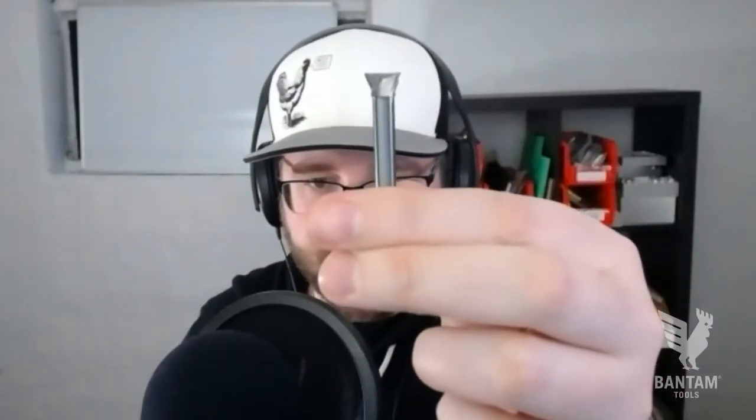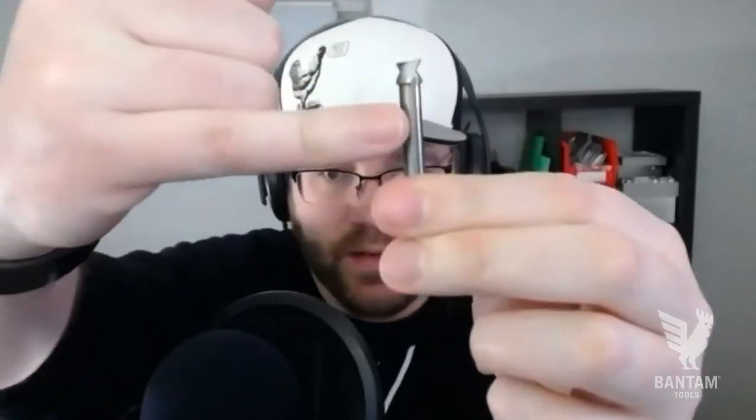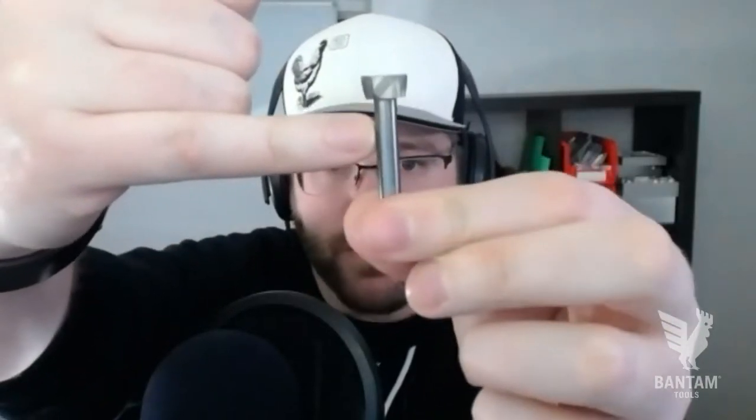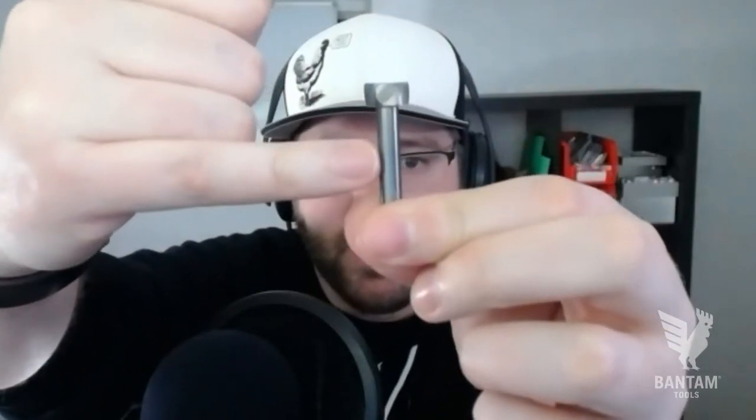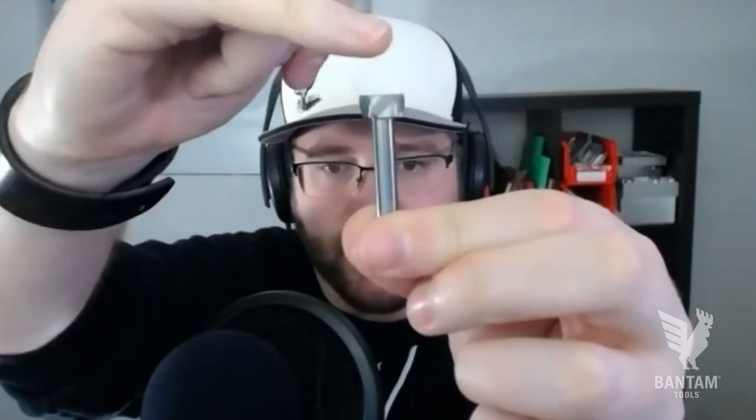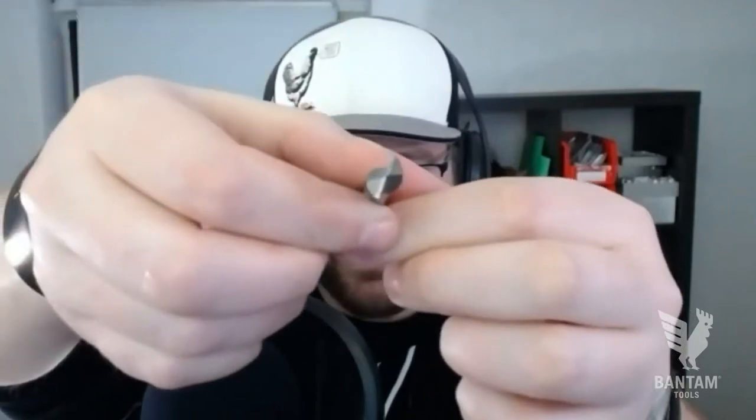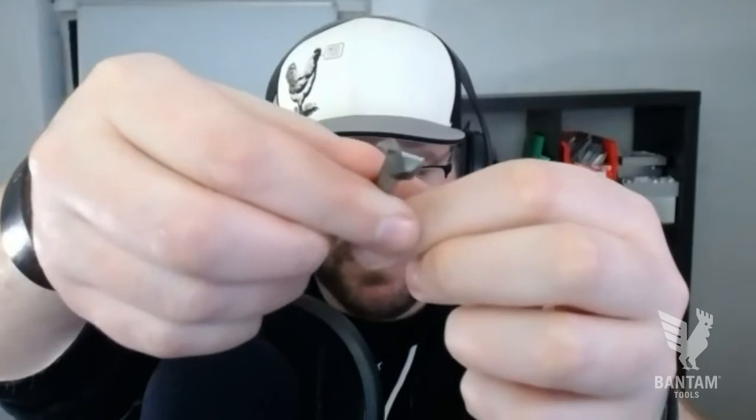But let's see, the Datron 12 millimeters. So this is a different type of flat end mill. This one's stepped, so it sticks out further than the actual shank of the mill, which is important. This is the shape of the mill. It's the shank, and then the actual cutting head is here. And this one is technically 2 flutes, meaning it has 2 different ways that it can expel the chips out from it. Because as you cut, it creates debris, and you want to get that out of the way.